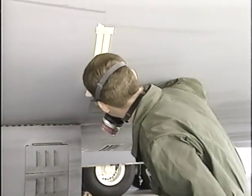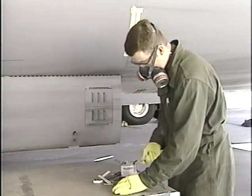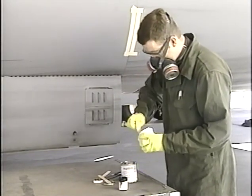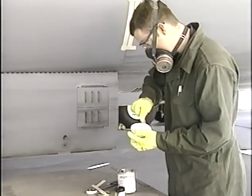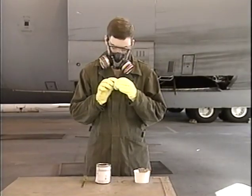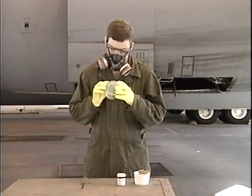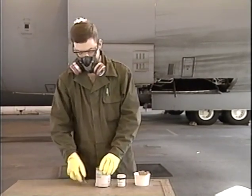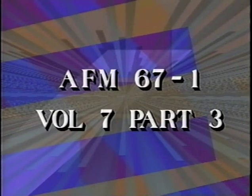Areas that require sealant also require special attention. Thoroughly prepare the surface before applying the new sealant. Correct mixing of the components is essential for proper curing and adhesion. Always check the shelf life listed on the label. There have been many cases where the products have failed or didn't provide the desired effects because the shelf life dates had expired. Additionally, shelf life and extension data can be found in AFM 67-1, Volume 7, Part 3.